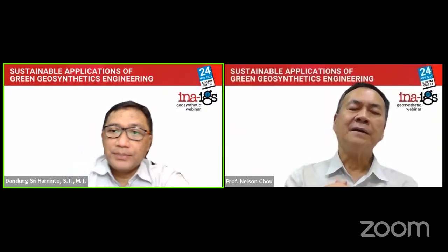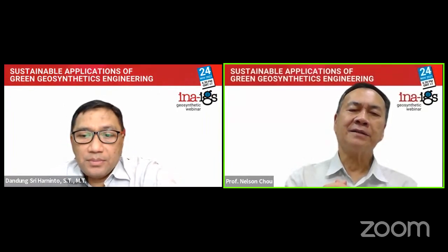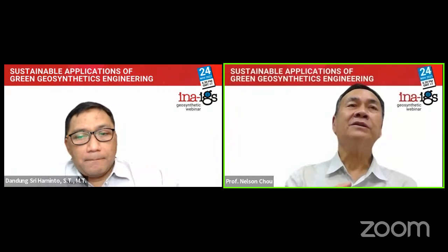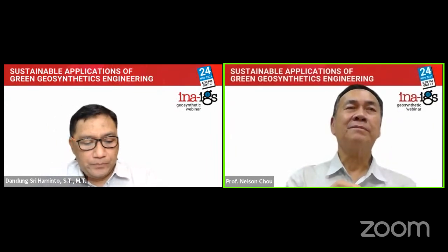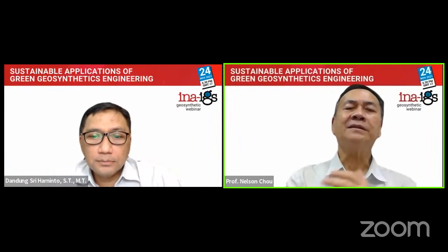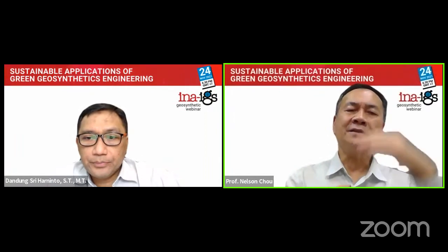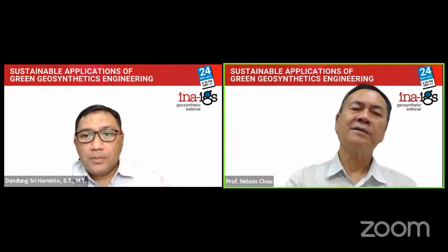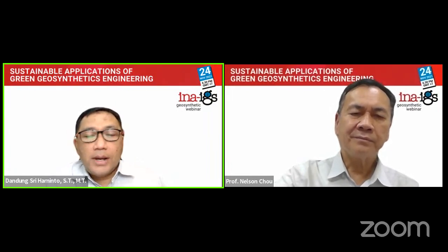Sometimes we put the geotube layers by layers to build a high dike. In that case, even though the upper portion, the first layer, may be subject to some degradation, the second layer will be okay. But we still try to cover the top layer with soil, then with some vegetation, to avoid sunshine. Yes, thank you.